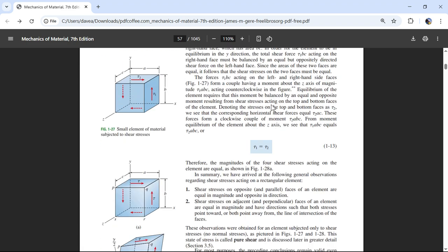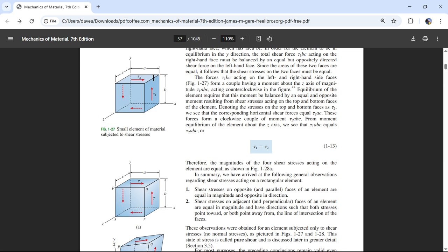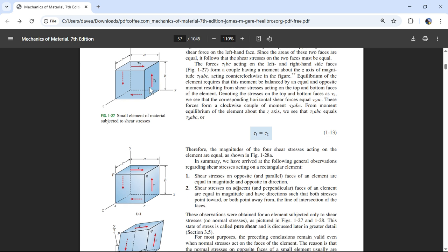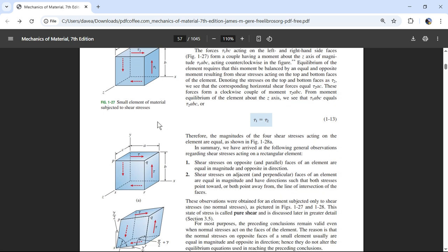That's what this diagram shows: these sideways pressures, these shear stresses, act on the cut face of that bolt. Shear pressure times the cross-sectional area gives us the force being applied.